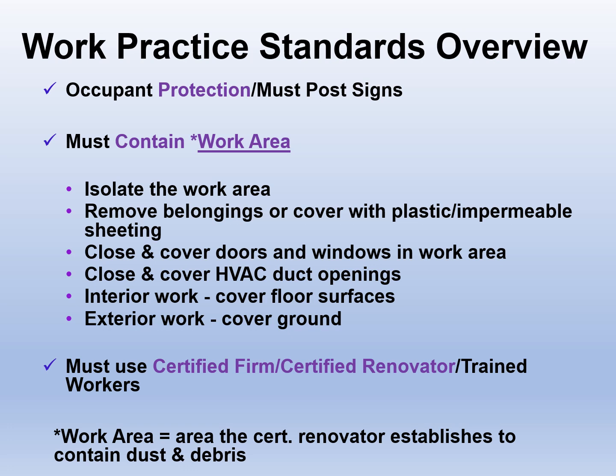They are removing belongings or covering with plastic impermeable sheeting, poly for short. Closing and covering doors and windows in the work area, as well as closing and covering the HVAC duct openings with critical barriers there, as well as any interior and exterior work.